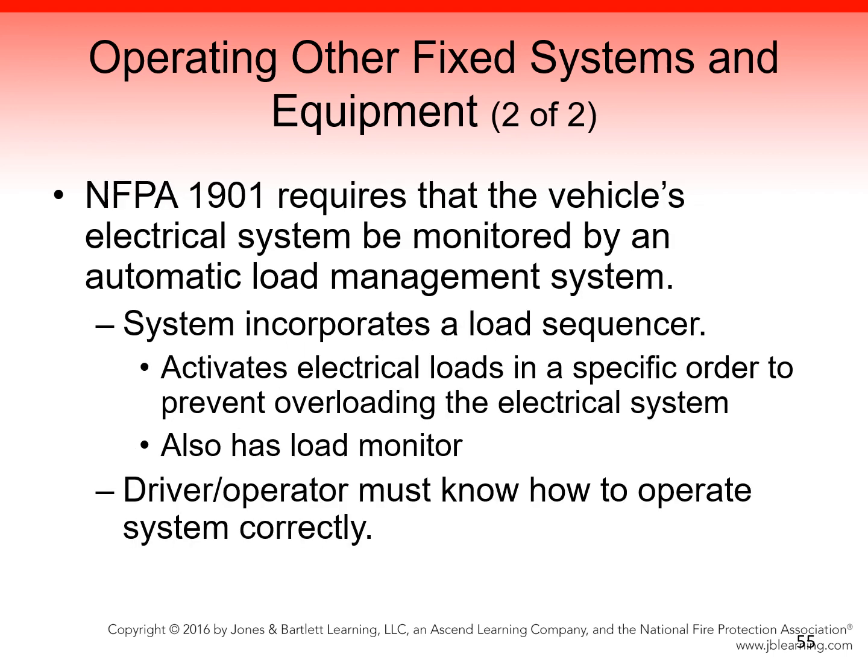National Fire Protection Association, NFPA 1901, requires that automotive fire apparatus have the vehicle's electrical system monitored by an automatic load management system, which is designed to protect the electrical system from needless damage while maintaining the operation of essential devices. Damage to the apparatus electrical system can occur if the total continuous electrical load exceeds the minimum continuous electrical output.